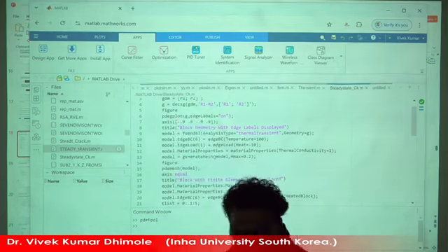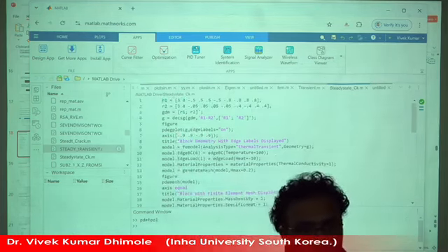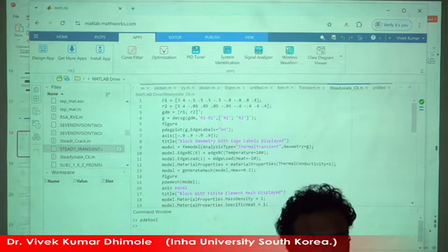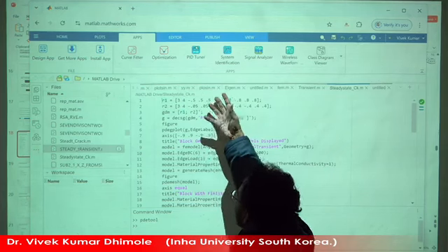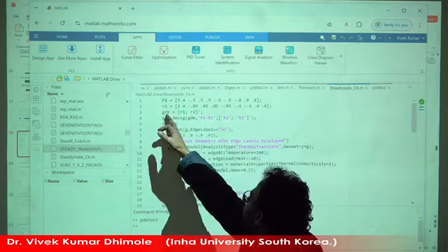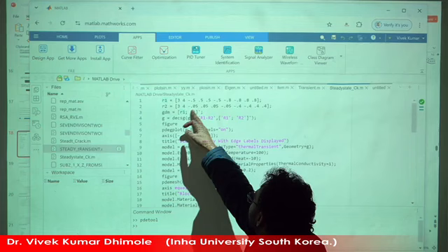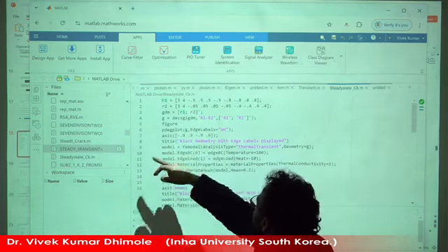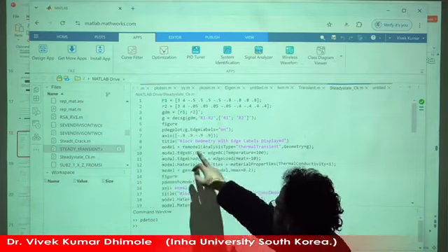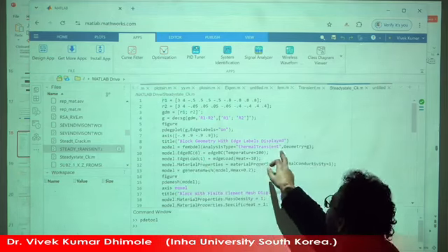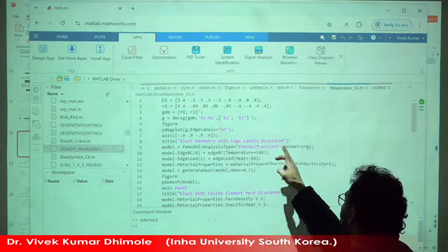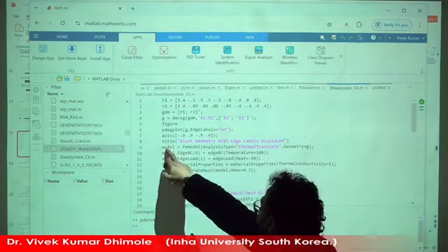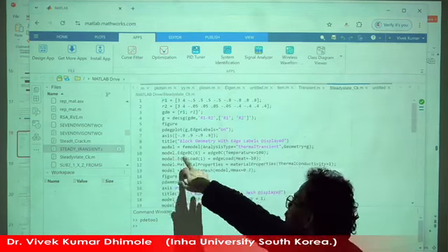First the model you define, right? So you are defining the model. This one. So this becomes your analysis domain, right? And you are defining the geometry from that, right? R1, R2. Then you are defining the figure of geometry. Then you have a model. Model you are creating, FEM model, analysis type thermal transient, not the static structure. Whatever you write, it will automatically pick up that model, right? The geometry condition. Then that model now takes the boundary conditions.